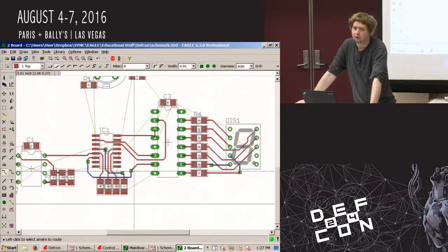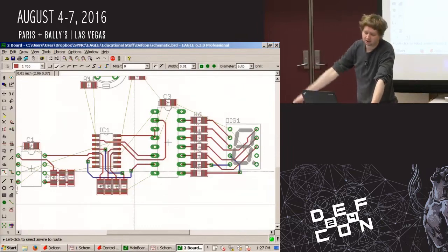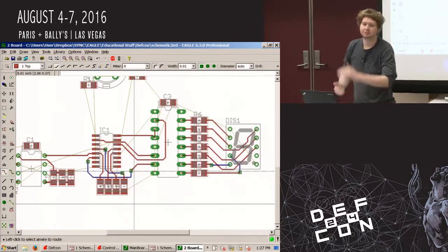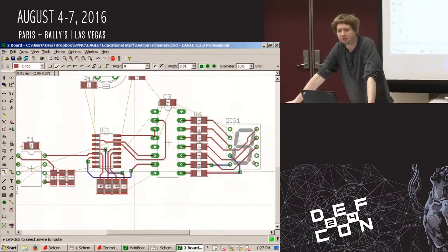And actually, a great story about that. I had an intern at work, and he needed to lay out a bunch of WS2812 LEDs, and this guy was so incompetent, I just gave up on the whole bypass capacitor thing. So he built his little project, and a month later I'm doing something on my scope, and I had it set to sweep fairly slowly. And every second, I would just see this massive burst of noise. His LEDs were putting out so much noise that my oscilloscope was acting as an antenna 2 meters away.